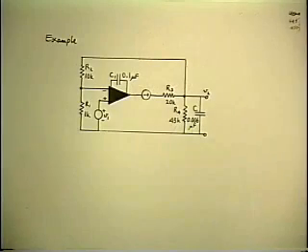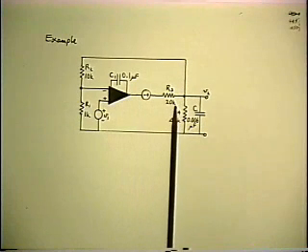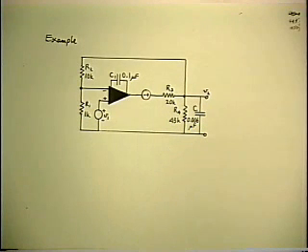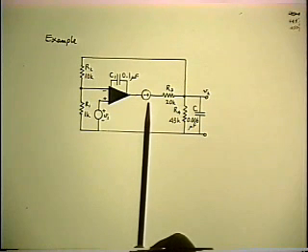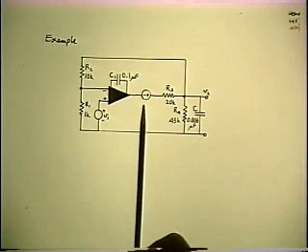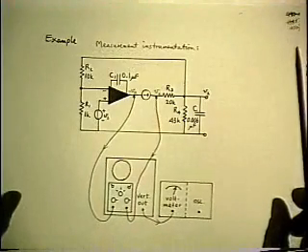We're now going to talk about how you measure a loop gain. So we're at the point in this particular problem now where we've predicted the loop gain we expect, and it has an adequate phase margin. So now we can go to the lab and breadboard the system and do the actual measurements. There's two parts to this. One part is how do you get the injected signal, and we'll talk about that in a moment. The other part is, once you've got the injected signal, how are you actually going to do the measurement? And we want to measure both magnitude and phase.